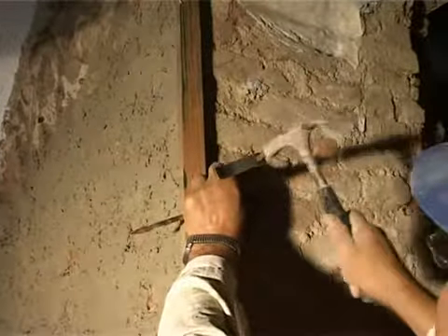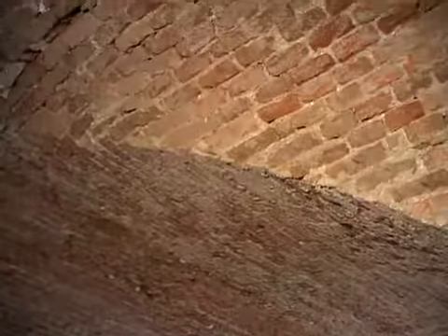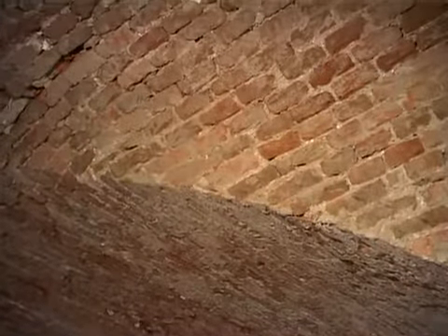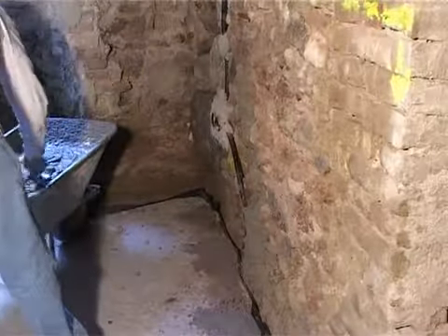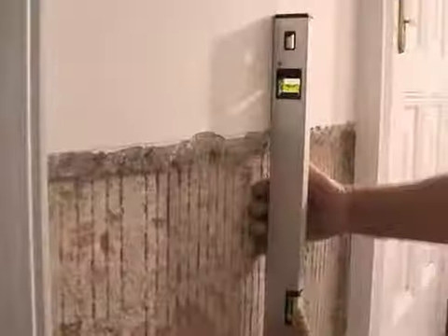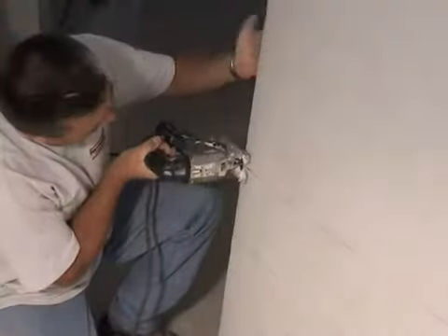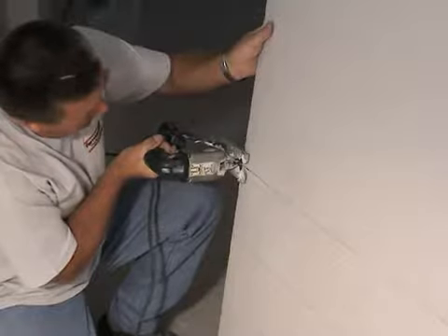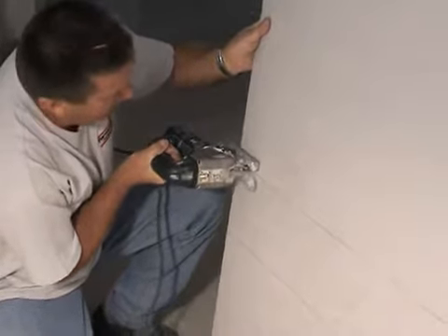If the wall merely needs a new coat of paint, it should be painted after the evaporation phase. According to the ÖNORM, the Austrian standard, and according to our long years of practical experience, the actual plaster renovation should be performed only after the wall has been dried. One thus avoids migration of the salts into the new plaster and consequent undesirable chemical reactions.